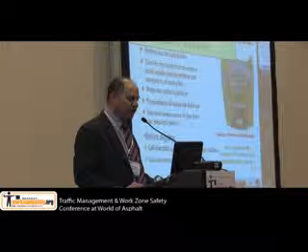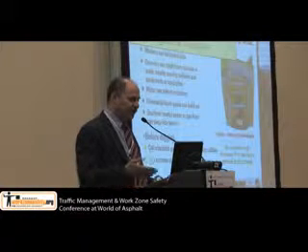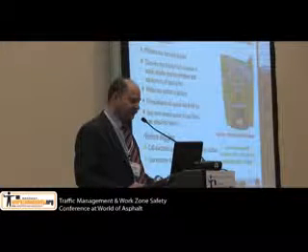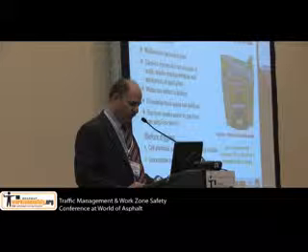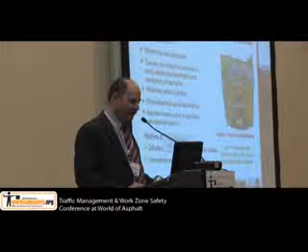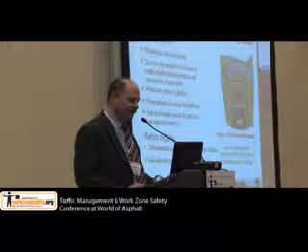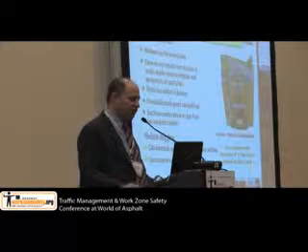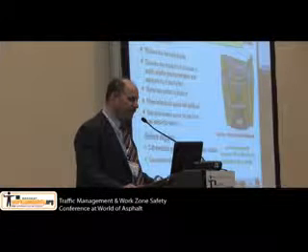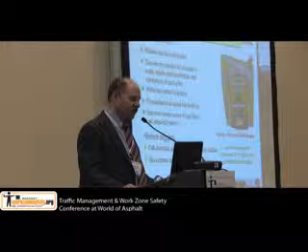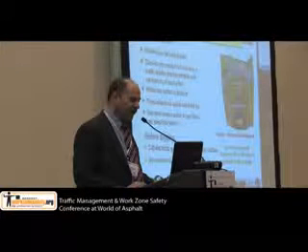So here's the OSHA regulation for trenches. It defines what a trench is. And here are some of the rules on calling before digging. The estimated location of the utility that may be expected to be encountered during excavation shall be determined prior to opening an excavation.